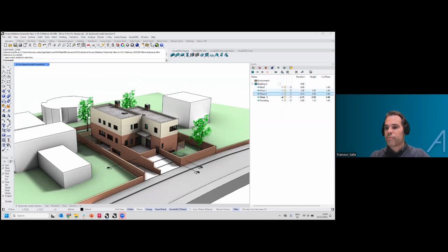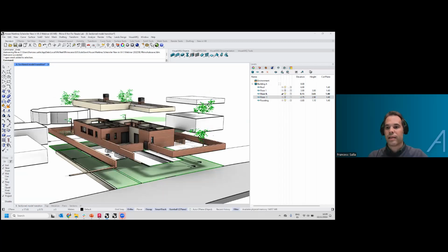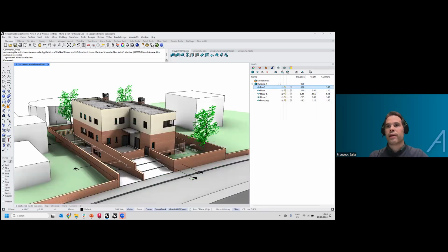We have added this column from where you can see the height of the level now, and you can also change the level elevation by typing the new height. And now it's easier to show and hide levels because you can hide levels individually, and levels that are not consecutive. So we can hide, for example, floor 1 and floor -1 in that model. Okay. So I'm going to show everything back again with this context menu that shows some additional options.